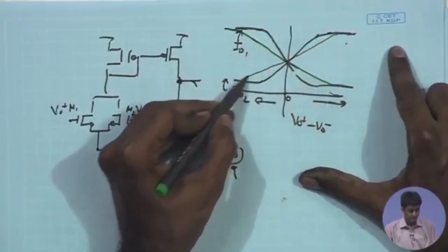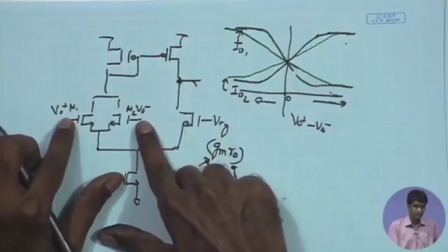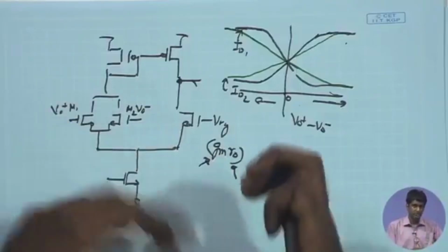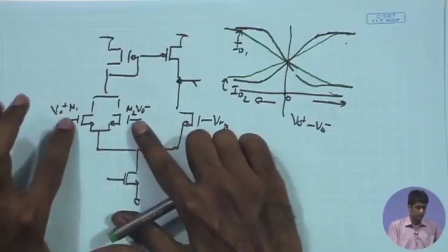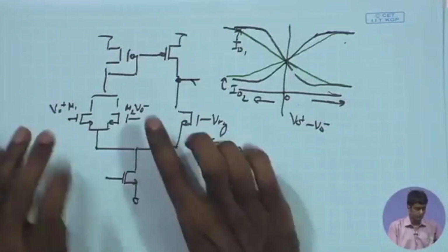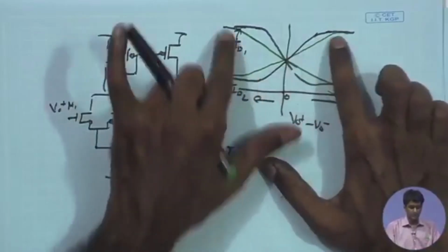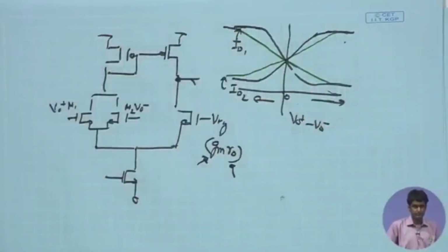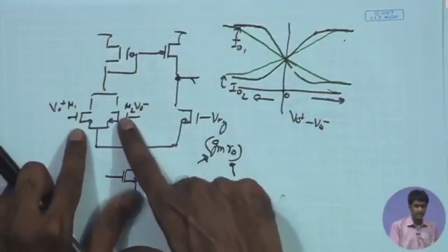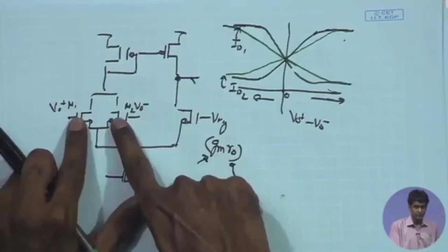That will ensure that it is able to handle a larger VO plus minus VO minus, especially if your output signal is becoming large, with a peak to peak signal of 1 volt, and you want it to be able to handle that large signal. We would like to go for a larger input handling capacity, and that can be achieved by significantly reducing the GM.